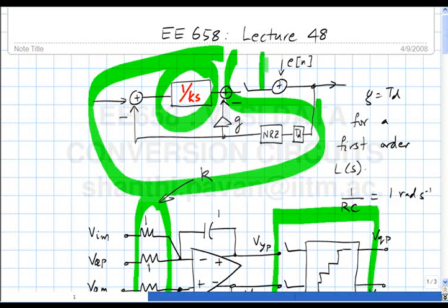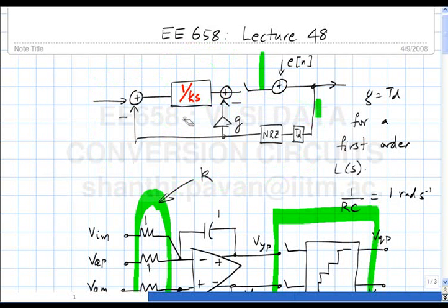That whole Z inverse by 1 minus Z inverse is basically this continuous time filter, which is some kind of con job where you make sure that at the sampling instant the outputs are what you want, at least in the nominal case.